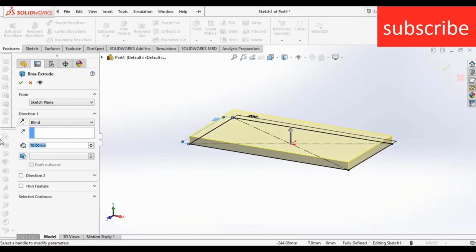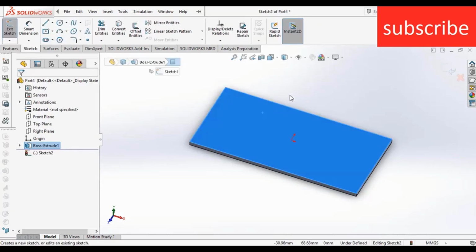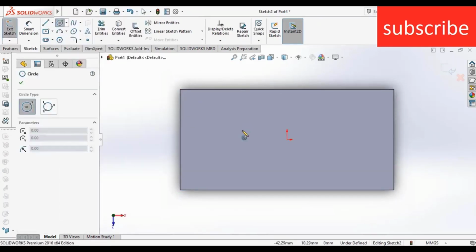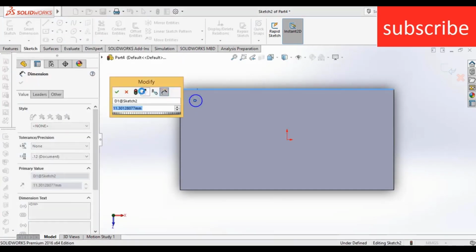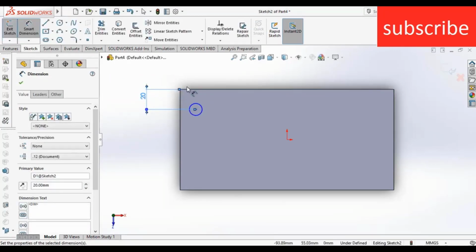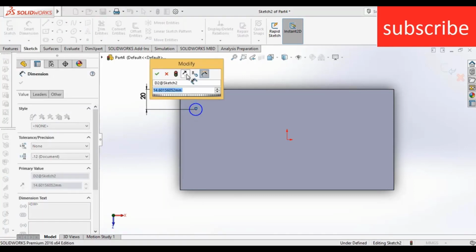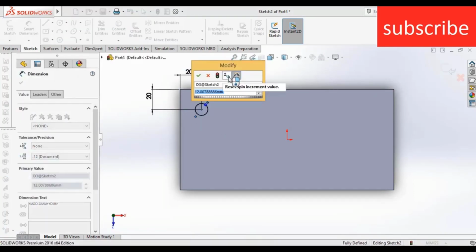Now you can reduce the thickness to 5 mm. After that, I am going to draw fins through which my heat is going to transfer. Say 20 mm and 20 mm, and the diameter is 10 mm.